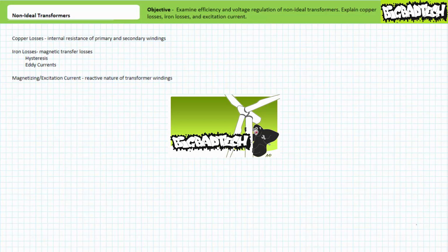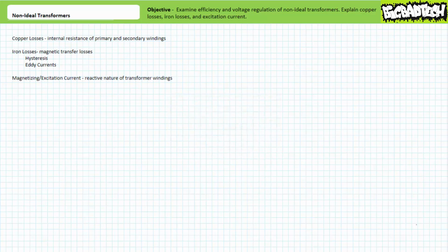presumption that transformers are 100% efficient devices, and all power input to the transformer is transferred to the output with no losses. This is obviously a lie, however, not one of gargantuan proportions. Transformers, even poorly made ones, are astoundingly efficient devices, principally because they're composed of no moving parts. This being said, they're not perfect, and we sometimes need to account for these slight imperfections using different models of non-ideal transformers. It's worth noting these approximations of non-ideal transformers are simple models at best, and are not high-fidelity approximations.